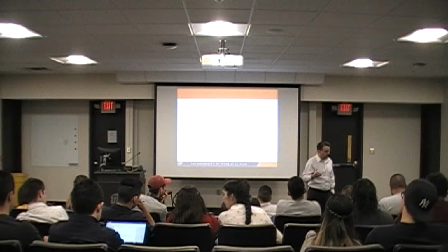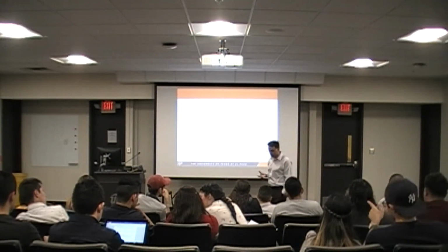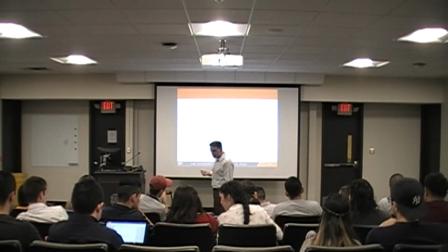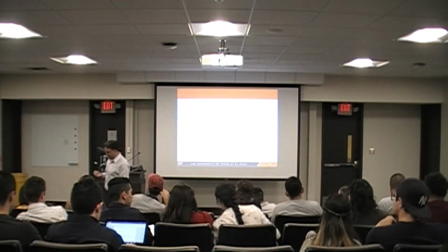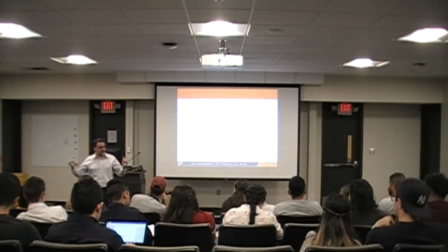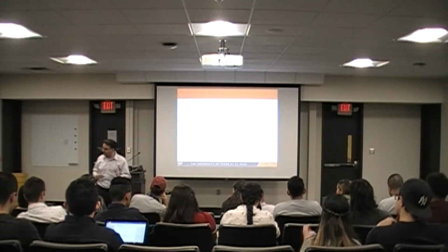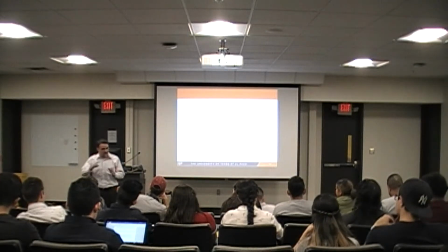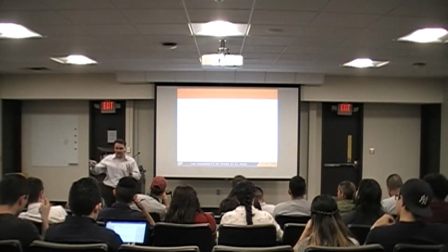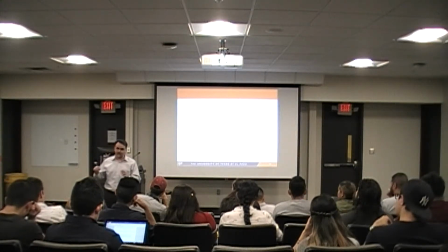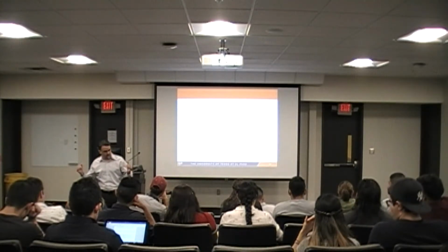So remember your Mohr circle. Remind me what the x-axis was, what the y-axis was in the Mohr circle. Normal stress on your x-axis and shear stress on your y-axis. Yes, as Jeremiah mentioned, on the x-axis you have normal stresses, and on the y-axis you have the shear stresses. And then you had your half circle, or full circle, but because it was symmetrical we go half circle, right? And then you have sigma vertical and sigma horizontal, those are sitting on the x-axis, right?